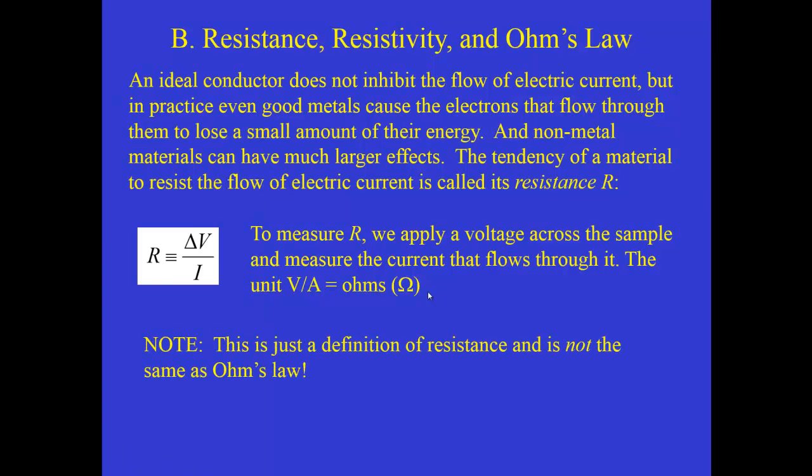Now, one note about this is simply the definition of resistance. It is not in any way a statement of Ohm's law. We'll get to Ohm's law in a minute when we talk about the behavior of real materials. This just says measure the voltage, divide by the measured current, and you get the resistance.